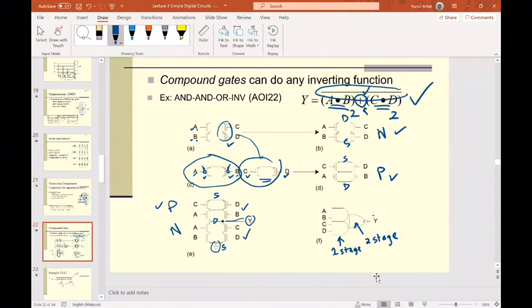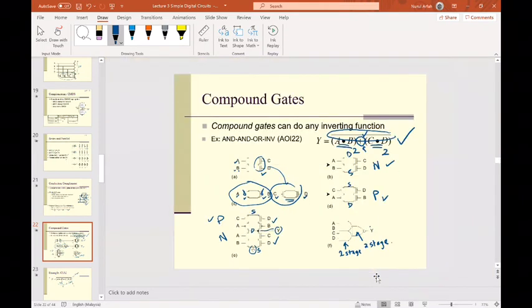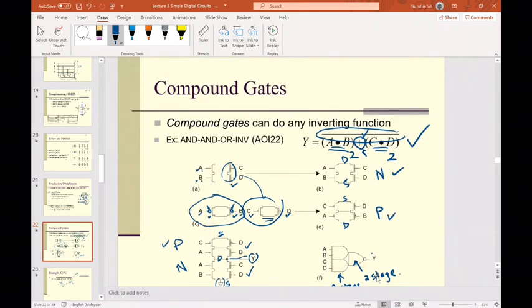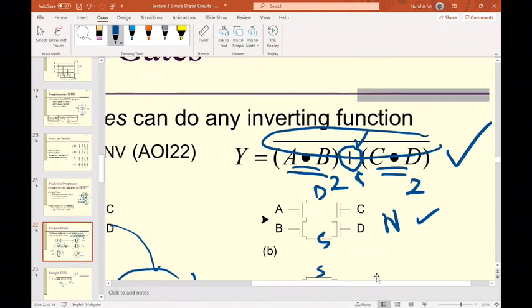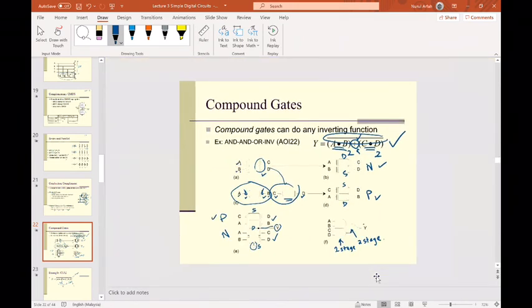So, ma'am? Yes? You need to have the PMOS side of things because we have the bar in the equation, is it? The bar is actually the negate side or the PMOS. This part is to negate the complementary, so that means you have to have a set of N for pull down and a set of P for pull up.